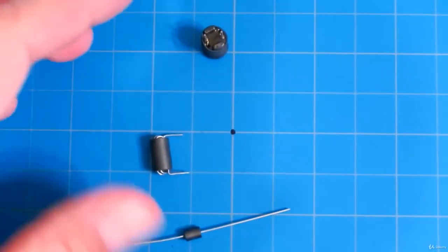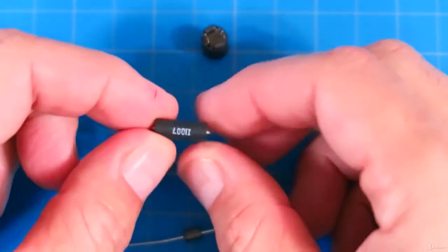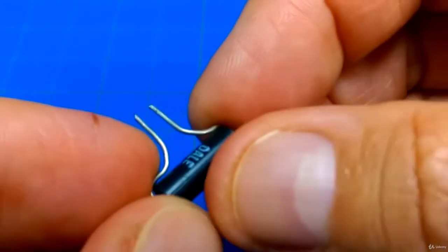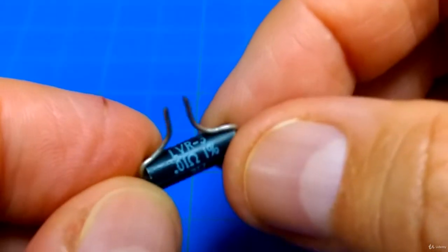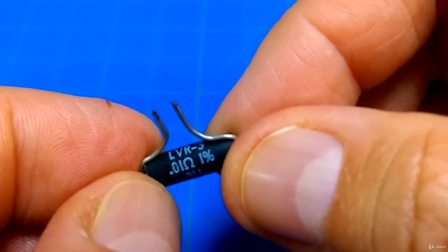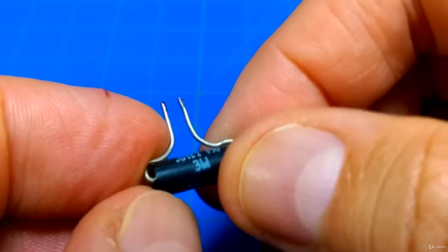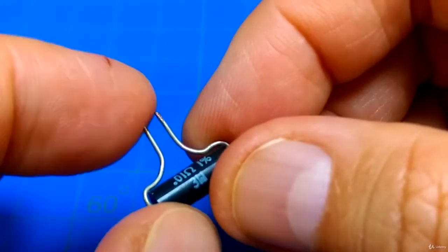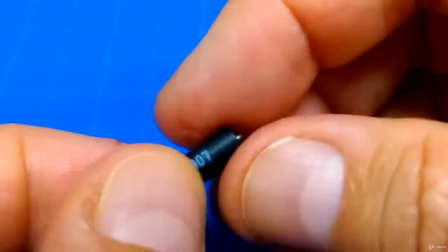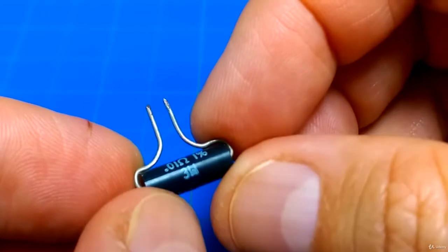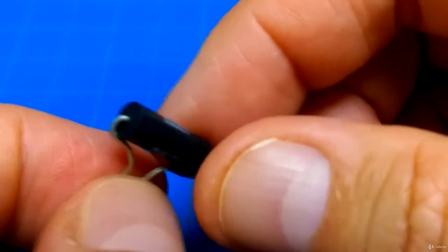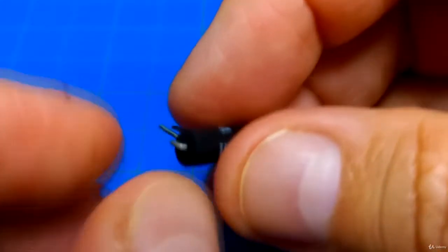All right, and before we move on, this is a precision resistor. Actually, let me show it to you over here zoomed in. This is only 0.01 ohms. Now, why on earth would you want a 0.01 ohm resistor? Well, that's usually to current sense. In a circuit, there'll be a current flowing through some part of your circuit, and you put this teeny tiny resistor in there. It'll have no effect on the circuit, but it'll generate a small voltage, and then we can sense that voltage with an analog-to-digital converter and compute how much current is flowing through the circuit.